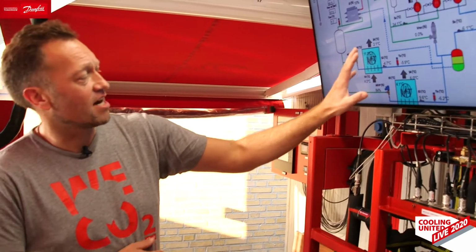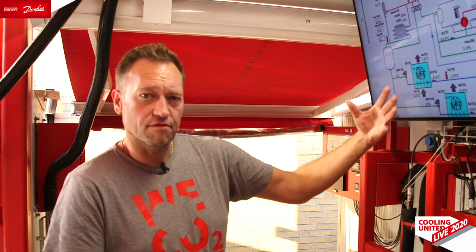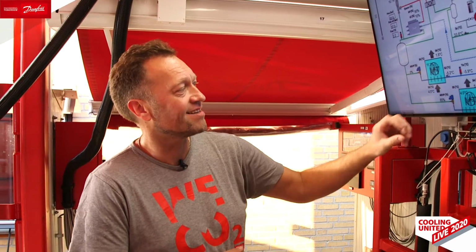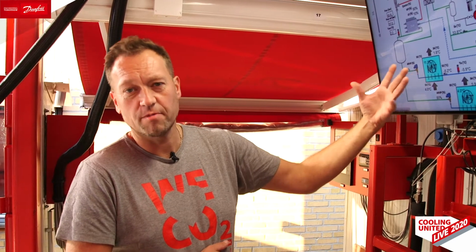And finally, you can argue that since the whole system has less refrigerant, we have a smaller accumulator, then also the traditional receiver in the system can possibly be dimensioned smaller. So this is the first cost aspect, you can say.